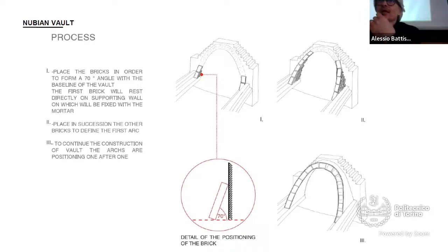Each material is a problem, because it's not easy to bring building material inside Gaza, as the Israeli army doesn't permit it easily. So we did it with these techniques, which work quite well. You basically have to put bricks in place one by one with this inclination, and these bricks push against the big wall that you build before the vault.